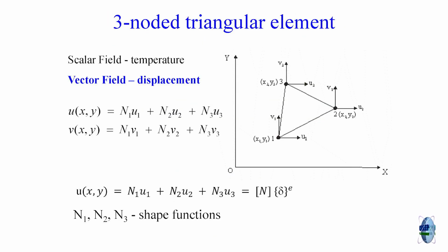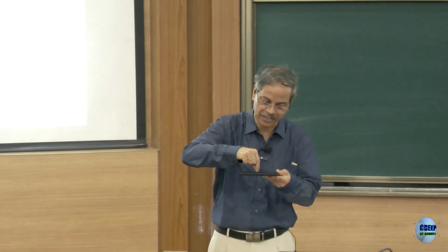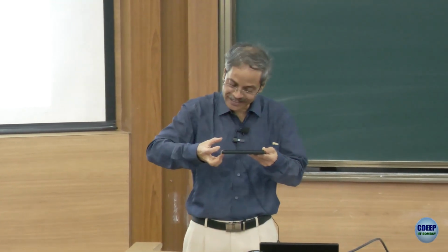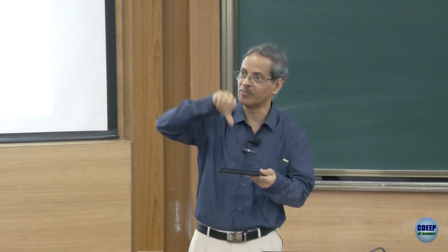We will review what we have done from the point of view of structural mechanics. So, we looked at a simple 3-node triangle element. Now, when we say two-dimensional structural mechanics problems, please remember our earlier discussion. We are saying that the deformations are in one plane only. x direction is u displacement, y direction is v displacement for any point P in the system. It is subjected to forces only in that plane, not perpendicular to the plane, no deformation, no force.